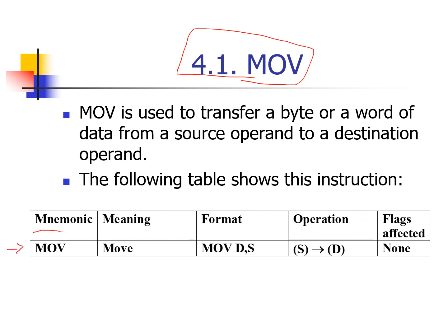The mnemonic code is MOV, assembly code, which means we are going to move data from a source S to a destination D. So the content of the source goes to the destination. We're copying the data from the source to the destination without affecting the data in the source. So after executing this instruction, the data in the source will be kept as is, and as we previously mentioned, it does not affect the flag bits.